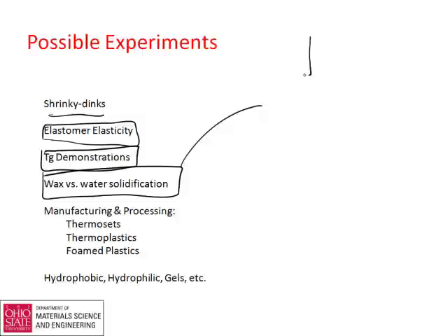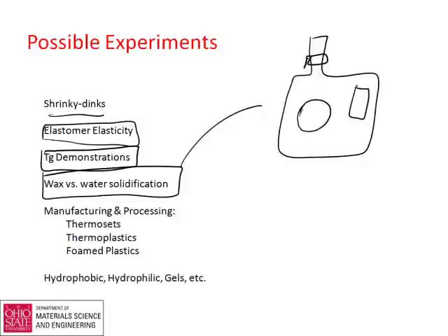My favorite demo is you take a milk jug, and you can take a hair dryer to it, and this is part of the ASM demo. Take a region and concentrate on that. Take it till it goes from milky color to clear.